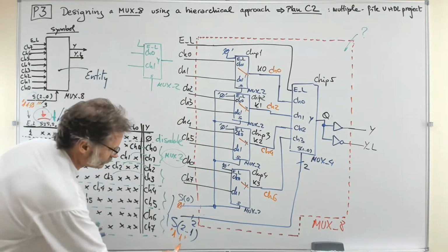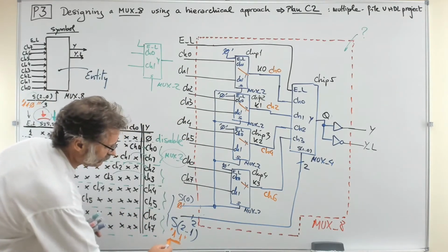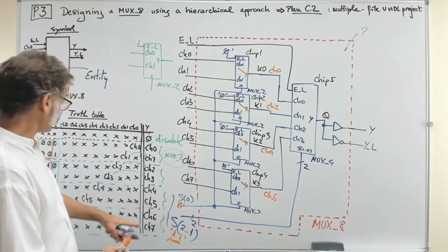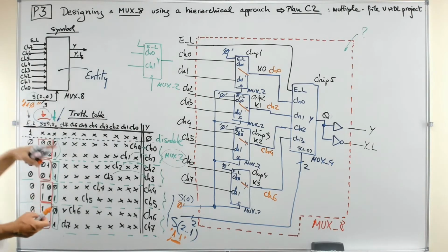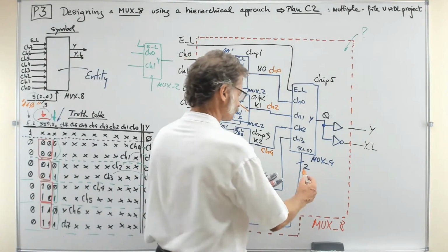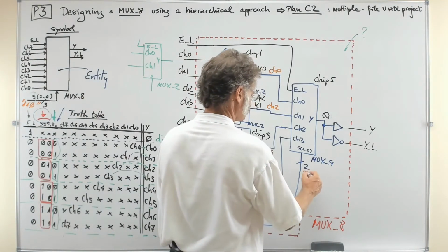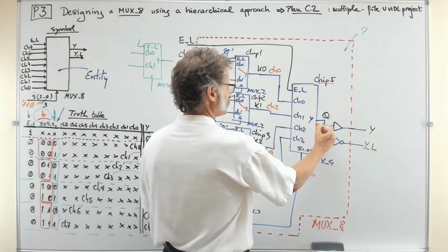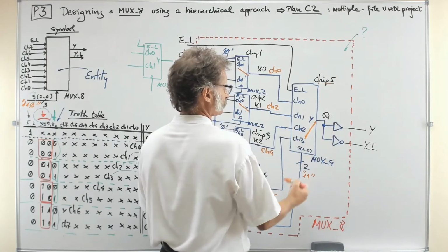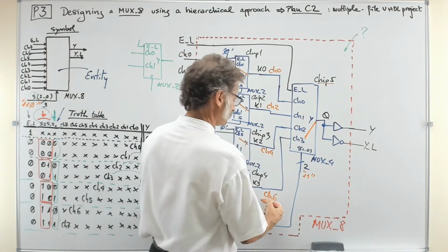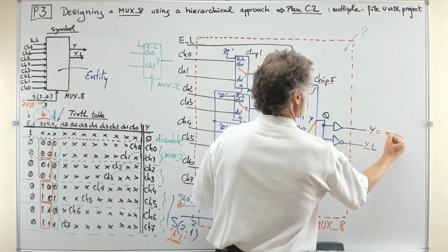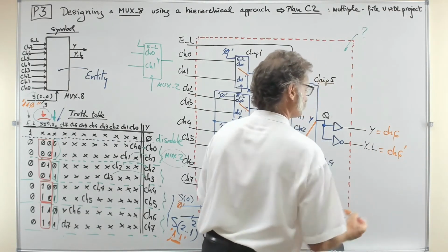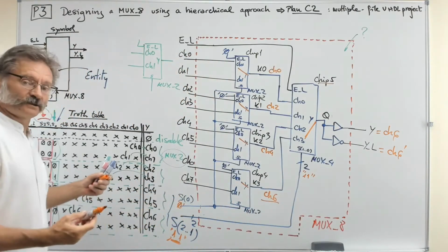But then what goes next is you clicking 1 in the other. Well, it's your input, right? 110, as you see in the table. But now this 1 goes straight to this second circuit here, the chip number 5. And what happens? 1 is a 3. So what you are selecting is the channel 3. So in the end, the channel 6 is the one that goes to the output. And this is the channel 6 data not. So this is what you want.